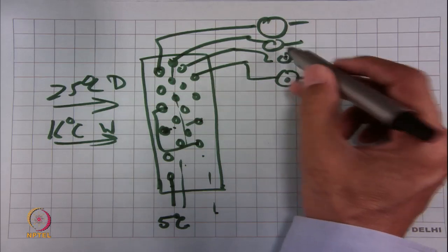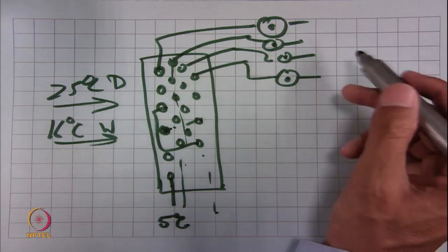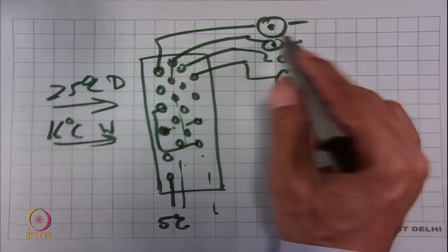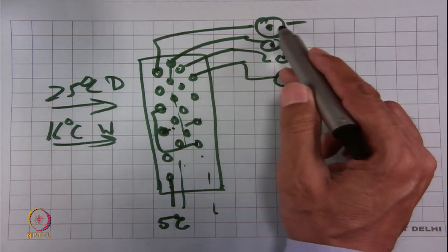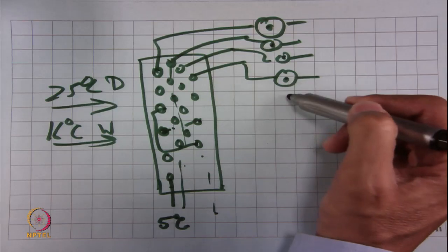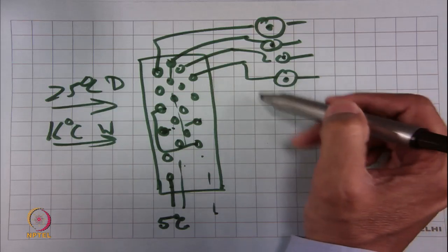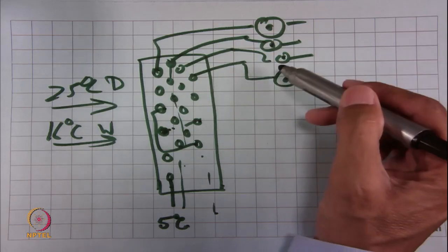The indicator which is in the center changes color based on whether there is moisture or not, and that is a separate requirement for a refrigeration system. And the other part is you can see whether you are getting 100% vapor or a mixture of vapor and liquid. This setup enabled us to look at which circuit was overfed with refrigerant and which circuit was starved of refrigerant when we were doing the circuit balancing.